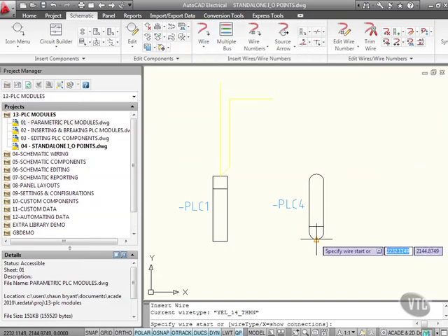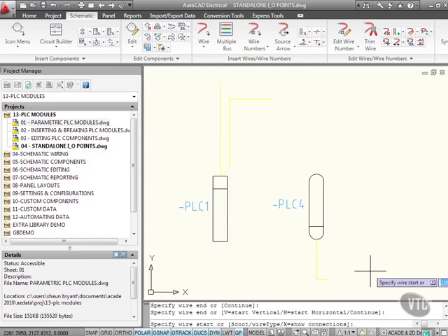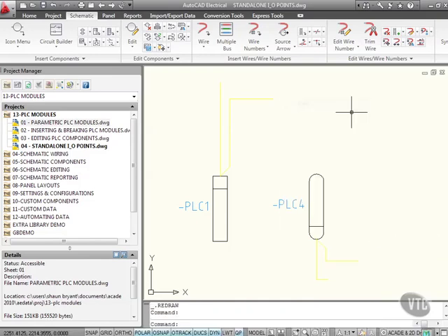Now let's do some wiring off of that one. So if I come off of here and pick the next point along here, the midpoint snap, and come that way, that wire comes off of there. If I try and start a wire this end, does the same as the in one. Can you see that? Right click and enter to finish the wiring there.